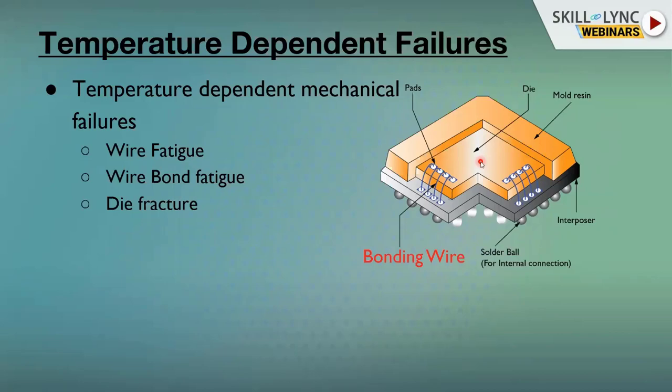You can correlate this with, for example, an aluminum rod that you bend to and fro. Maybe the load was not high enough to crack the aluminum rod, but the to and fro motion made it possible. So repetitive loads are catastrophic for components.